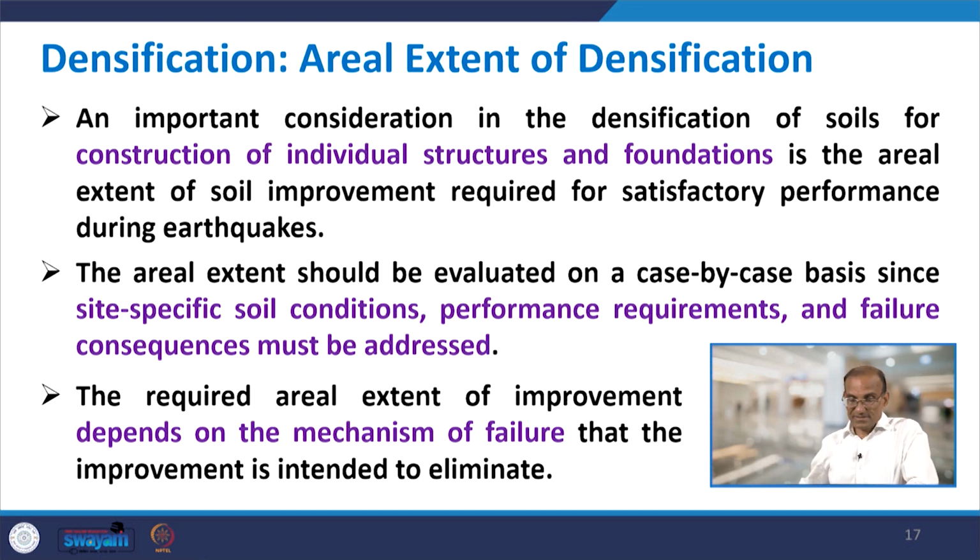So, this aerial is related to area, though it can be seen from the top, and it is related to area, how much area is covered. An important consideration in the densification of soils for construction of individual structures and foundations is the aerial extent of soil improvement which is required for satisfactory performance during earthquake.